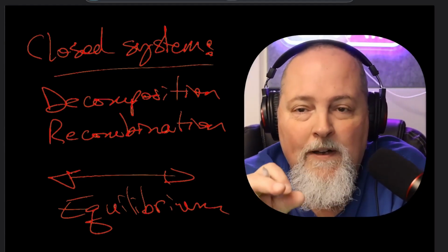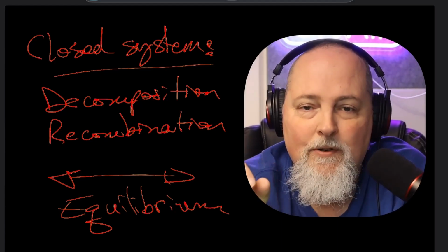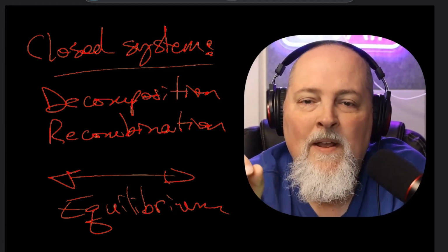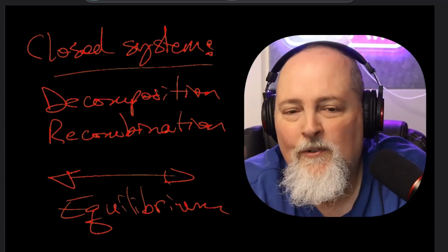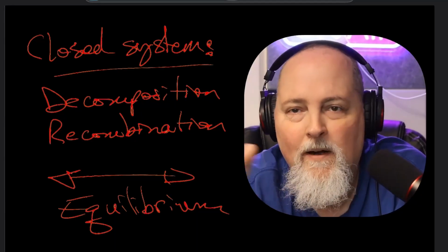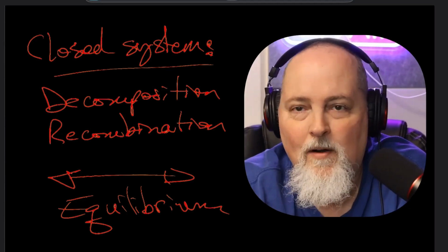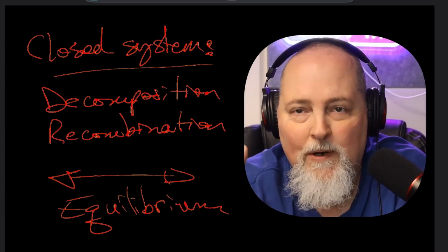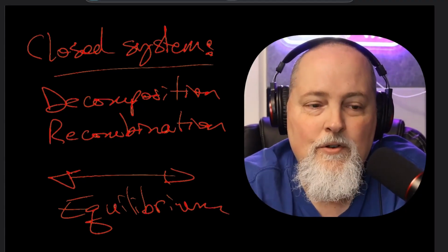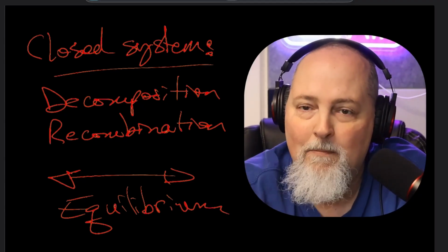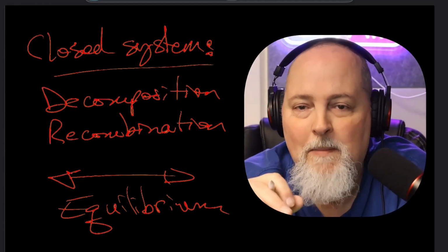In your briefing sheet, it also identifies lithium hydroxide as the pH control chemical in the PWR, and boric acid as the reactivity control chemical. That can be a little different depending on the plant. Like in the Navy, we never added lithium hydroxide, and our reactors on the submarine were pressurized water reactors. We added ammonia. I think in your student text, you'll find it talks about ammonia, and in your briefing sheet, it talks about lithium hydroxide.